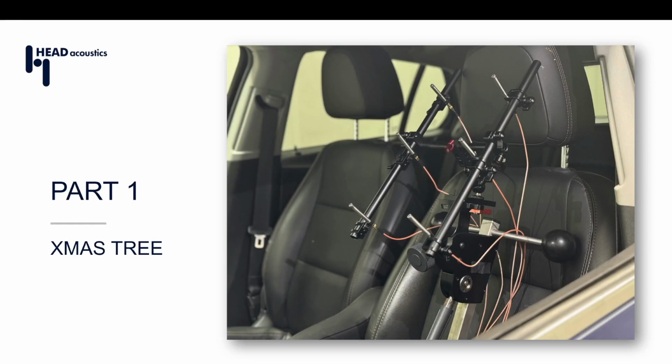The Christmas tree is conducted using 6 microphones. The underlying principle being you get 3 sets of ears at different driver sizes, 5th percentile, 50th percentile, and 95th percentile. And with one measurement, you can take advantage of spatial averaging. Having an array that covers average head sizes is great, and for automotive applications, we tend to have a very well-defined head placement, close to the headrest, that can help guide the positioning of the array.